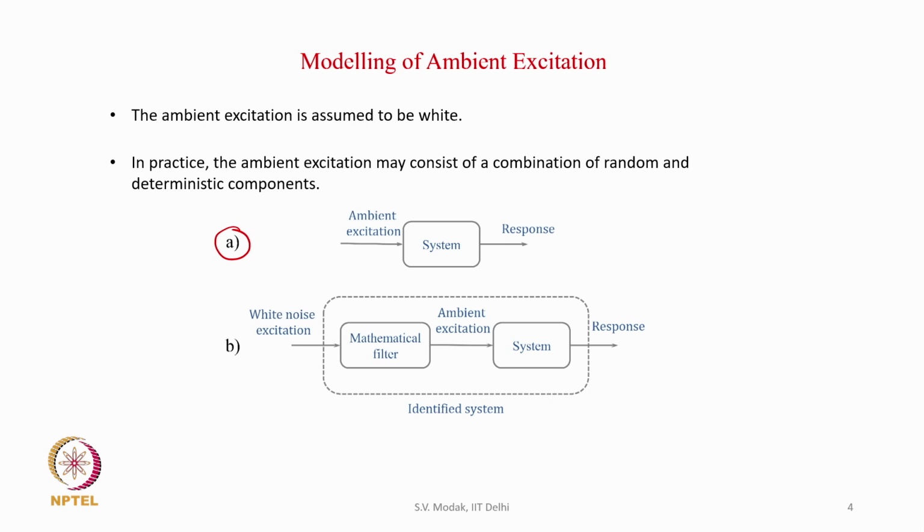This ambient excitation generates the ambient response. This ambient excitation is the actual ambient excitation acting on the system, and now this may consist of the random component as well as some deterministic components in general, right, and therefore, the response would also contain random response as well as response corresponding to the deterministic components in the ambient excitation. Now, in part B of the figure, what we see is the implication of the assumption of white noise input acting on the system in case of operational analysis.